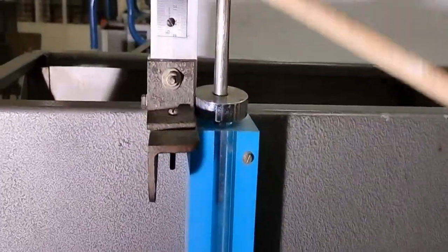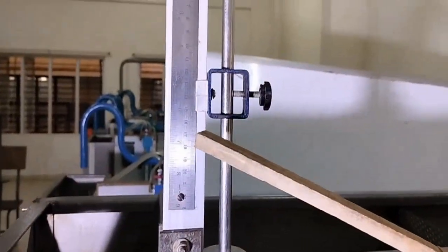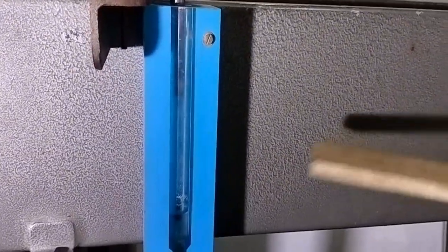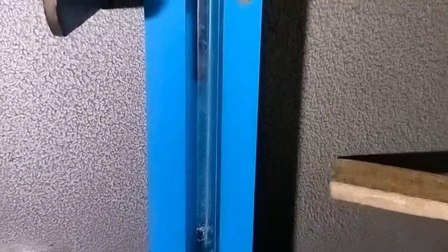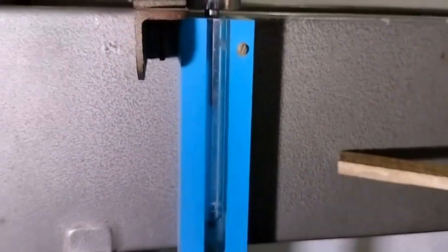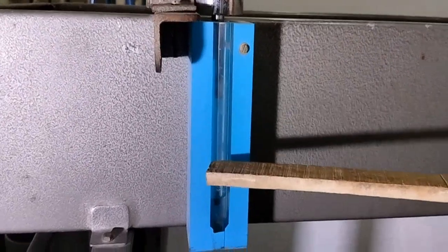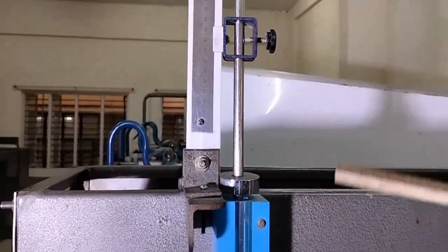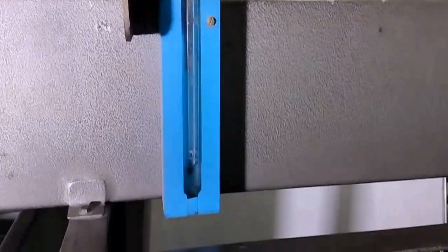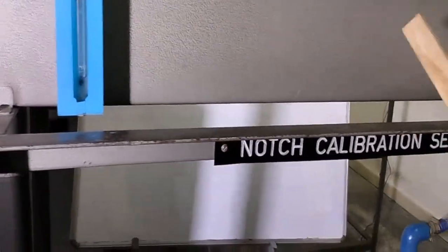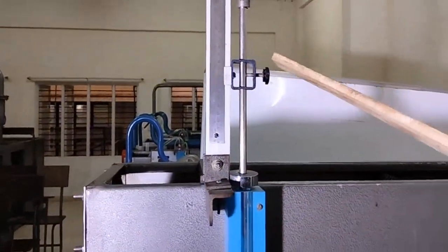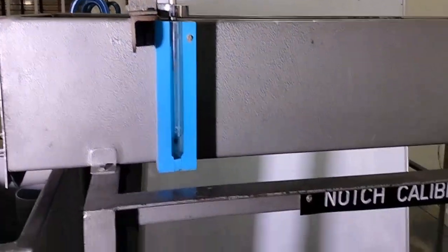Here the scale is there, which we call the surface gauge level. First, we have to set it to the crest level. The needle is there, and it should touch the crest level. That becomes our reference. After the water rises, the needle is raised and the corresponding reading should be taken. So the parts of the experiment I already explained: this is the canal, that side is the notch, and the scale is required to measure that height.